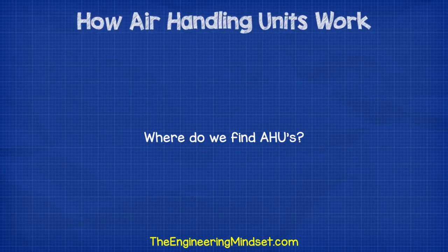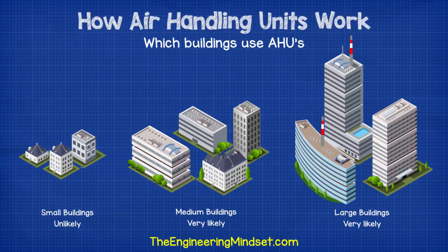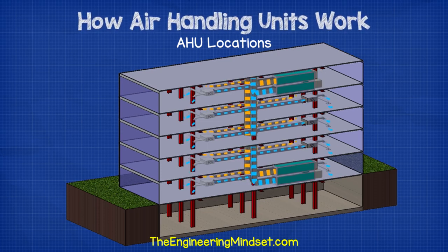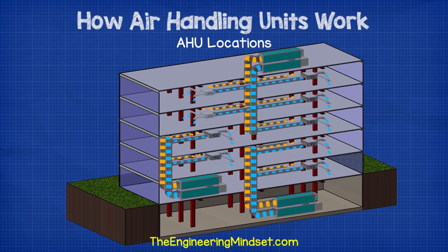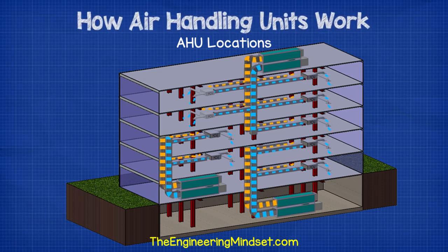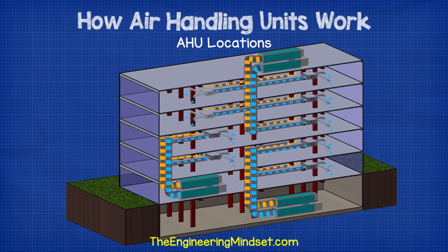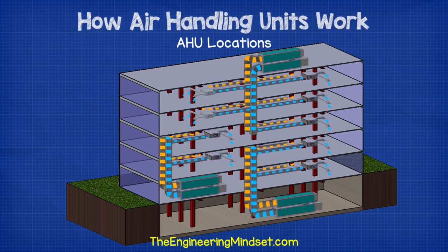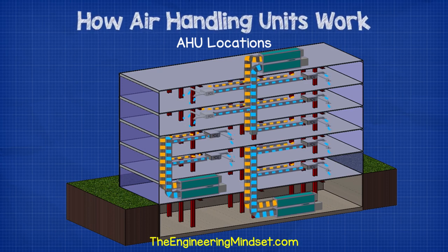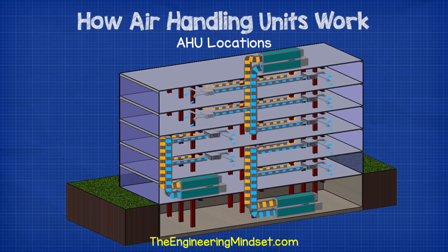So where do we find air handling units? Air handling units, which usually have the acronym of AHU, are found in medium to large commercial and industrial buildings. They are usually located in the basement, on the roof, or on the floors of a building, and many large buildings will likely have a mixture of all of these. AHUs will serve a specified area or zone within a building, such as the east side or office areas from floors 1 to 10, or perhaps a single purpose such as just the building's toilets. Therefore, it's very common to find multiple AHUs around a building.